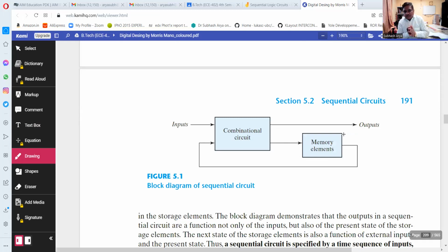so far as the definition of sequential logic is concerned, a sequential logic circuit is a digital circuit in which the output is a function of input as well as the past output, or previous output. In a combination logic circuit, output is a function of only input conditions.